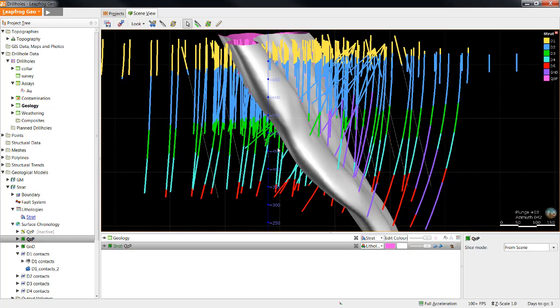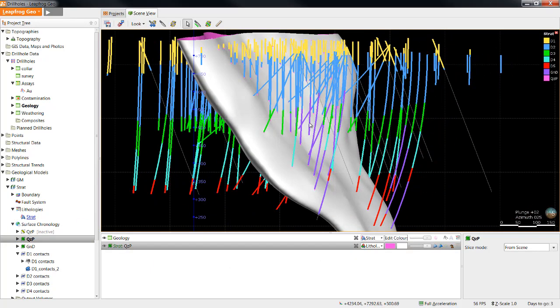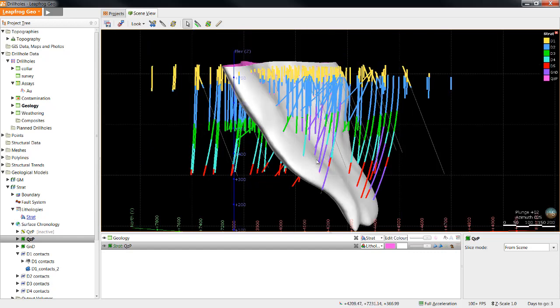After snapping to the drill holes if required, I recommend applying a trend to the surface. By default, surfaces are built in an isotropic environment, so connectivity in any direction isn't preferred over any other direction. Applying a trend introduces anisotropy that can help to connect intervals in the desired orientation. Applying a global or structural trend is covered in different video tutorials.